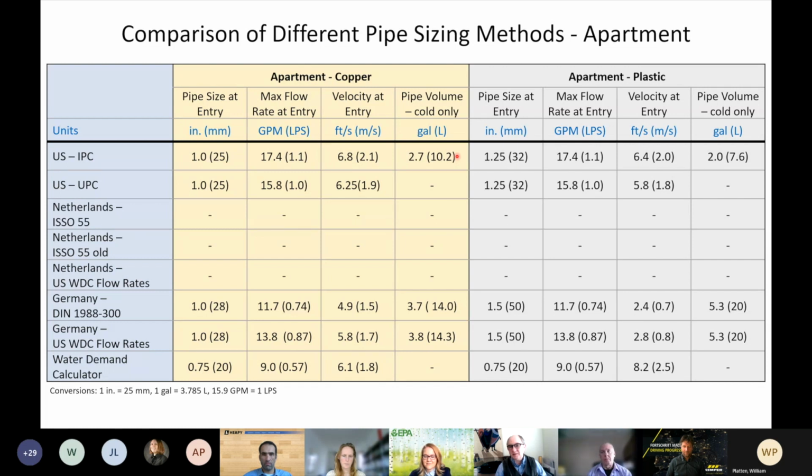Bigger diameter pipes, correct me if I'm wrong, the velocity is slower, so probably more things drop out of solution and settle to the bottom of whatever's horizontal. What else is there? Yeah, I mean, you touched on the larger diameter is a slower flow rate. So if you're thinking about the actual flow rate, what's really happening, in a larger pipe, it's going to be a lower velocity.